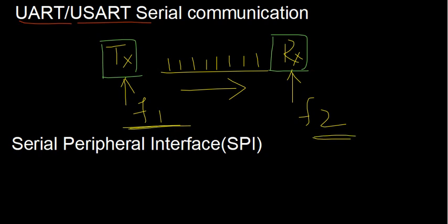Okay, but here this system is again useful, wherein you need the data to be transmitted over a long distance, where it is not possible for us to connect both the transmitter and receiver physically with the same frequency clock, right. Sometimes if the distance is too much, it is not possible for us to connect both the transmitter and receiver with the same frequency. There probably this kind of methods are used. This is again by making use of the physical channels. You may use your telephone lines or any other kind of physical media through which the information is exchanged between the transmitter and receiver. Okay, so this is one thing.